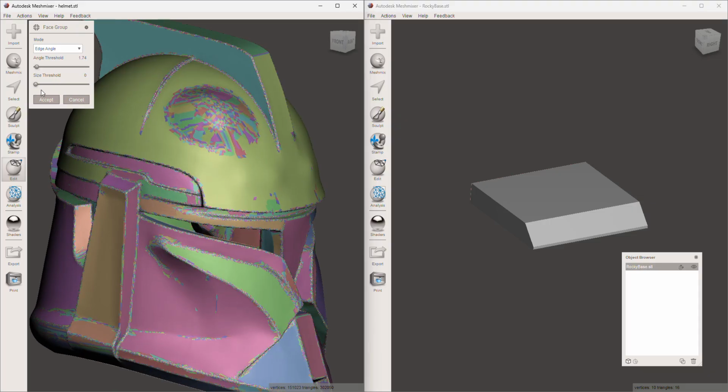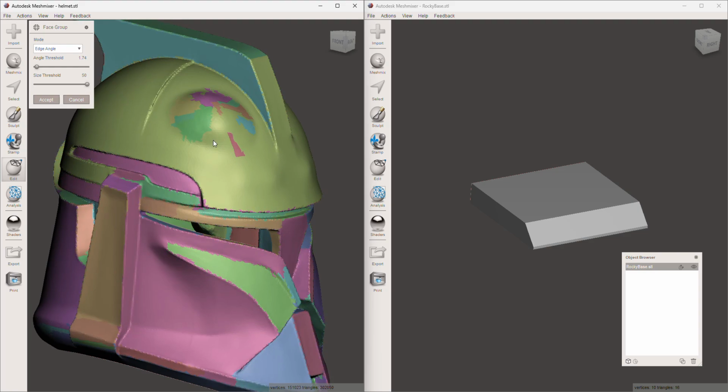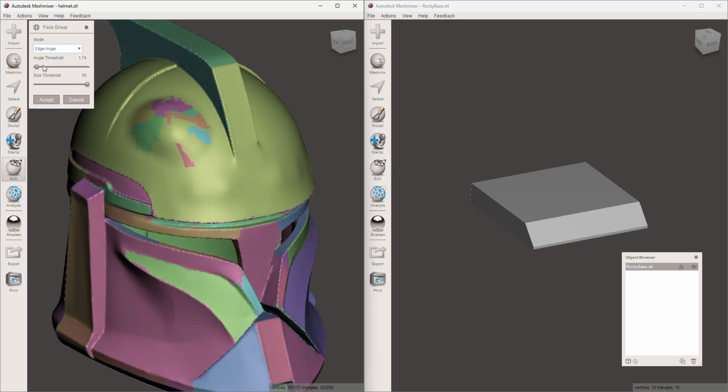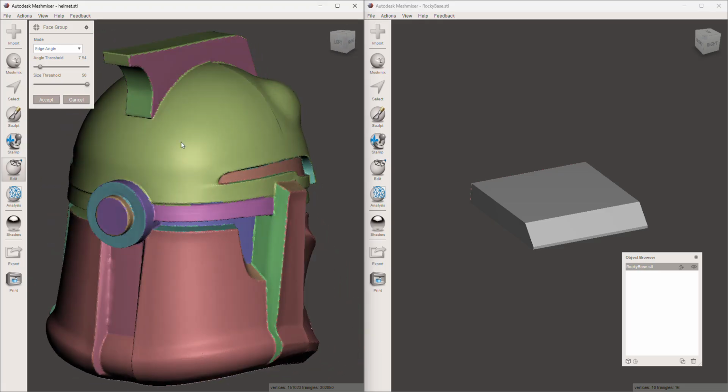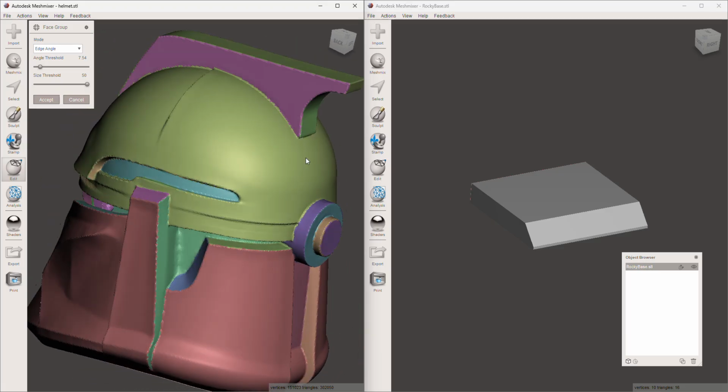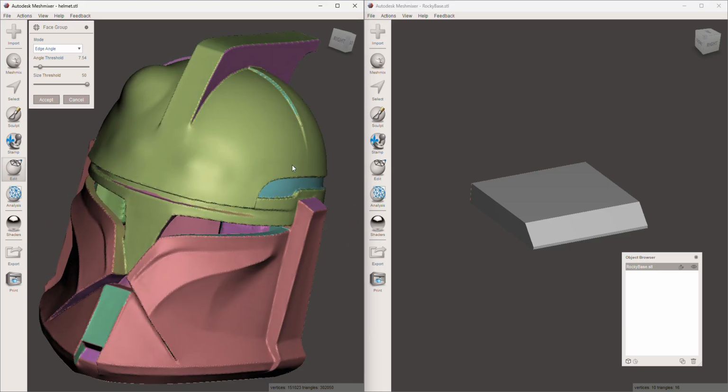Okay. I always change this as well because you'll see all these little dots appear because the threshold is very small. If you increase that to 50, most of those will disappear. So now it picks up larger panels. A good size is usually around 8 to 10 to pick up certain things. But again, so now we've got better isolated features without having to do individual selections.